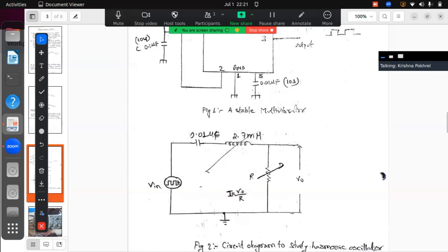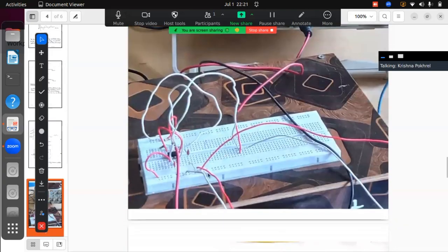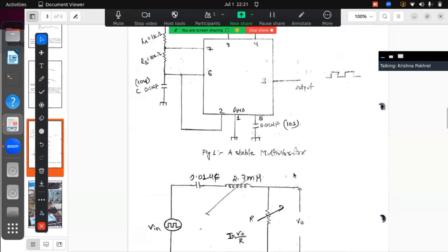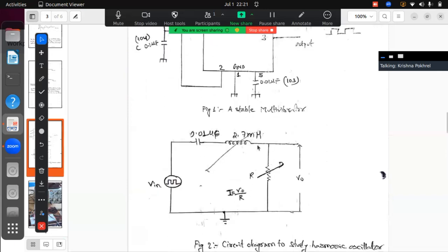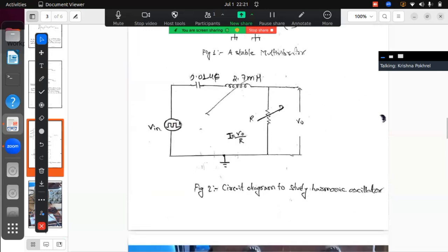This ground means ground. Finished. We have one wire over here. This one is a common ground. This ground and this ground should be common, because it should come from this power generator box. So make sure about this, whether the systems are connected or not. I recommend you do not proceed with this experiment, otherwise it will be much more complicated, before you get this output in an oscilloscope. Take one wire of the oscilloscope, red wire, to this 3 number, another wire to ground, and check this as an input. If you get this input, supply this input over here, and after that I will tell you what to take from here.